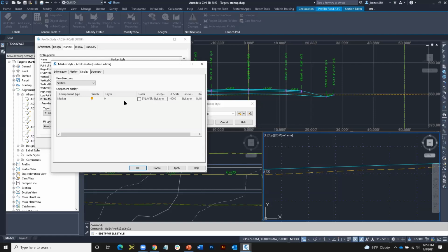I do this because when you create a marker like this, markers work just like a traditional AutoCAD block. Now, AutoCAD block, if you ever created a block, we may do a couple sessions on blocks here in the future. If you draw your geometry on layer 0 and you convert that geometry into a block, that block will assume the properties of any layer that it's inserted on. So rather than having 10 identical block symbols that all have different properties for colors, we can create one universal block by drawing it on layer 0, and it will assume the properties of the layer that it's inserted on.